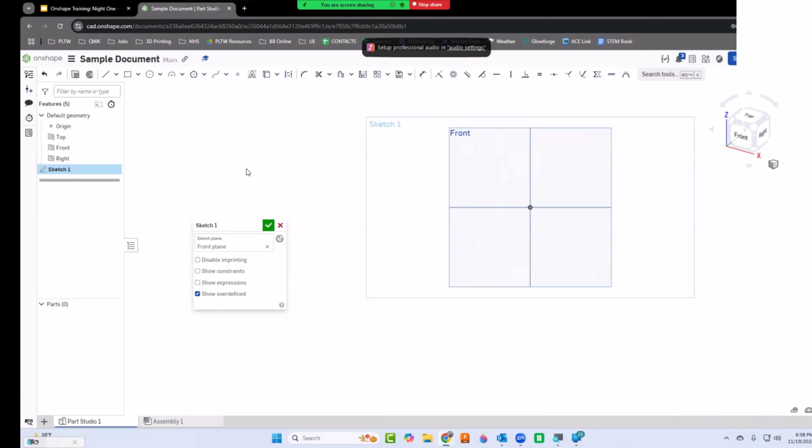All right. So the first thing I always do with my kids is I start them simple. I'm like, hey, let's just make a cylinder. Okay. So I'm going to start. Here's a circle up at the top in my sketch area. I'll click that circle. I like to tell my kids, hey, let's start in the origin when we can. We want to pick up a good habit. So I'll click there. For now, I'm not even going to use sizing. I'm just going to draw. I'm going to click the green check mark for finish sketch.